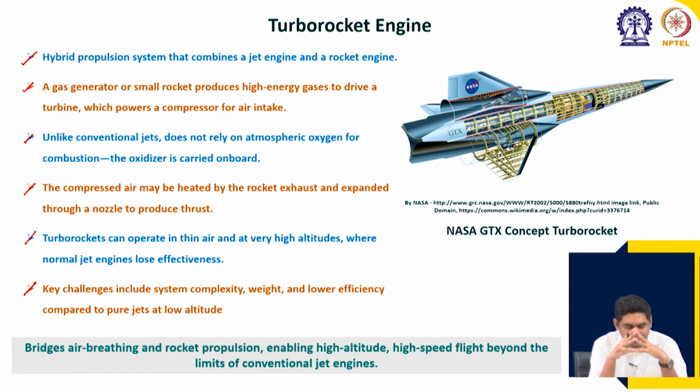There are key challenges, like the system becoming too complex. Weight is an issue compared to simple jet engines, because now you are carrying the oxidizer, and efficiency will be lower as compared to pure jets at low altitude. Of course, this is going to be designed with a different application in mind, where space travel is also possible. So, in summary, this turbo rocket engine bridges the gap between air breathing and rocket propulsion engines.